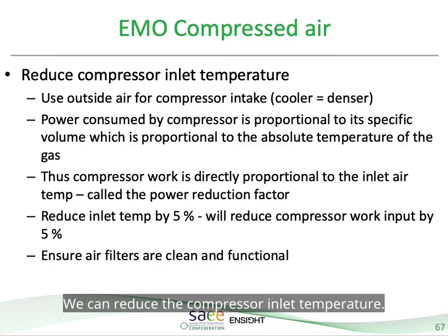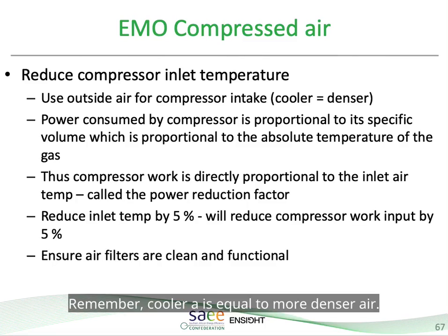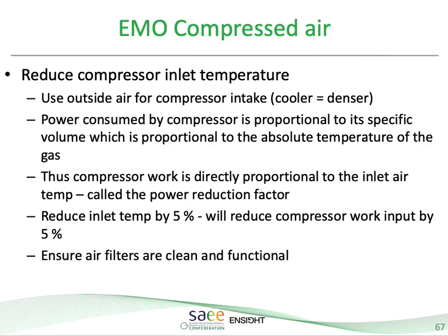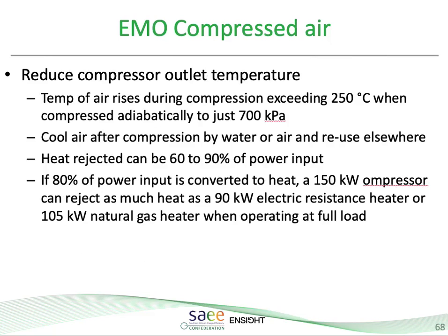We can reduce the compressor inlet temperature. Remember, cooler air is denser air. Thus, power consumed by the compressor is proportional to its specific volume, which is proportional to the absolute temperature of the air. Ensure that all filters for air are very clean.